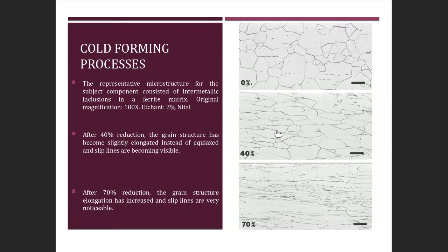Remember, each one of these grains is its own crystal. That's why this is a polycrystalline material. So they're all going to be oriented differently, giving you these grain boundaries. In this particular case, the slip planes happen to be oriented, just for the sake of conversation, at about a 45-degree angle if you're looking at this being a perfect 180.